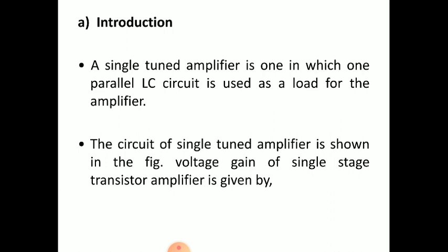And if you remember the frequency response of the single stage amplifier with RC coupling, it is very flat with constant gain in the bandwidth, that is in the mid frequency range. But if you remember the same basic amplifier with a transformer load, you can see in the frequency response there is a bump. That means there is a sudden increase in the gain at a particular frequency, that is f0, the resonant frequency.